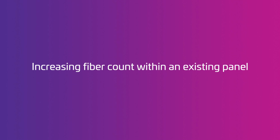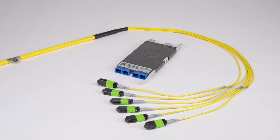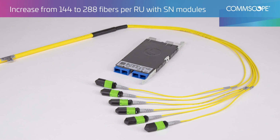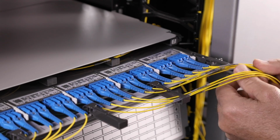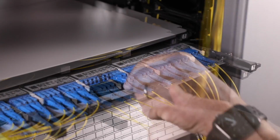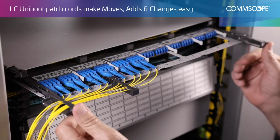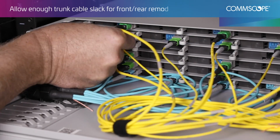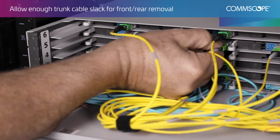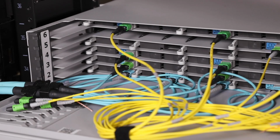What if you want to do something a little more involved, like increasing your fiber count within the panel? With Propel, if you're already using MPO 8 or MPO 16 single-mode trunks to LC duplex, you can go from 144 fibers to 288 per rack unit by just replacing the LC modules with SN modules. Take the patch cords out of the clips and remove the clips. Disconnect the LC patch cords from the MPO 8 modules. Disconnect the MPO 8 trunk connectors from the rear of the modules. Remove the modules by pulling on the pull arm and sliding them backwards or forward, depending on your installation.